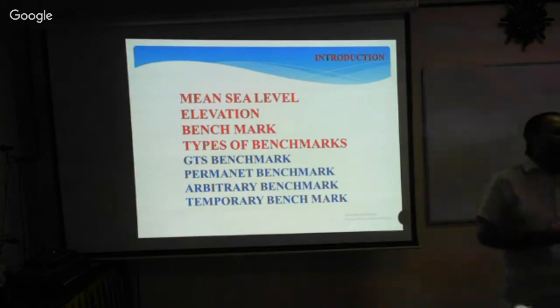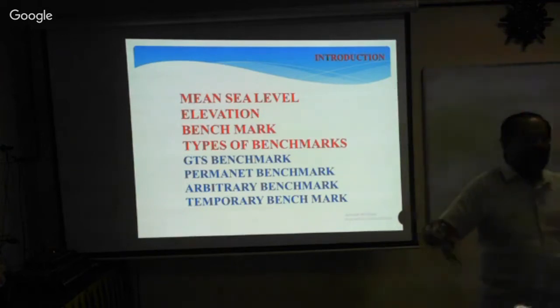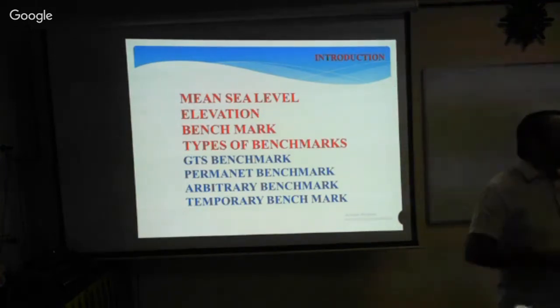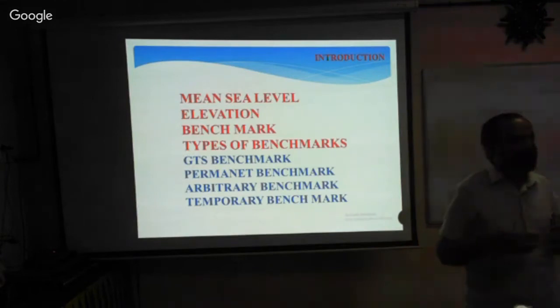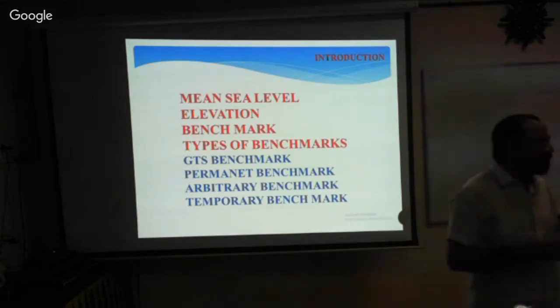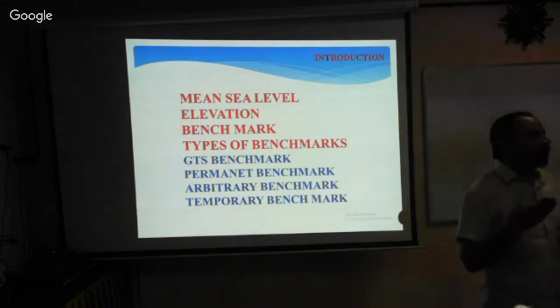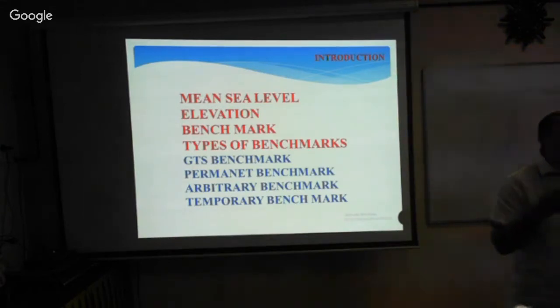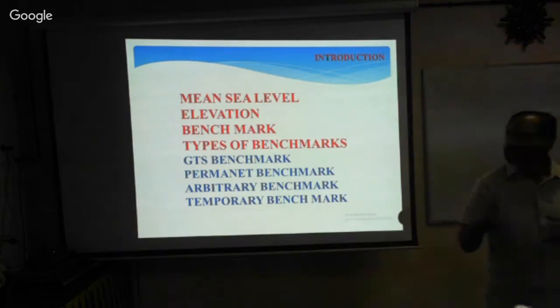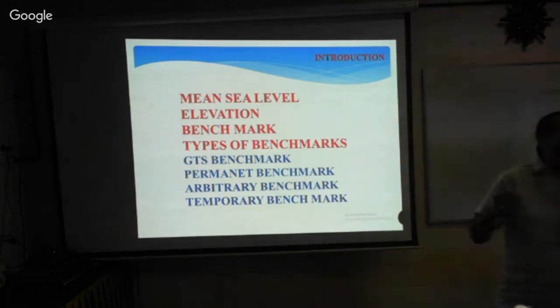Now, we have another one, the arbitrary benchmark. When you are in the forest, you go with all the equipment, all the instruments, to do some survey work. When you reach the site location, you need to establish your own benchmark, because nowhere in the forest will you find one, nobody has marked it. Neither a permanent benchmark nor a GTS mark is available in the forest.